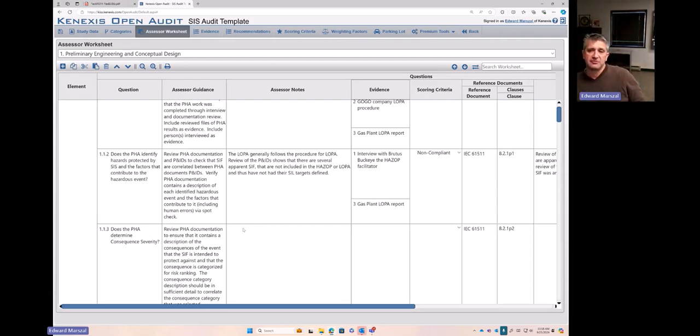A lot of times for medium projects, you wait until stage 3, right before you're ready to put oil in, before you're ready to introduce hazards to the process, before you do the functional safety assessment. But on larger projects, you might want to assess every step of the way so you don't carry an error for 6 months and have to go back and redo everything.